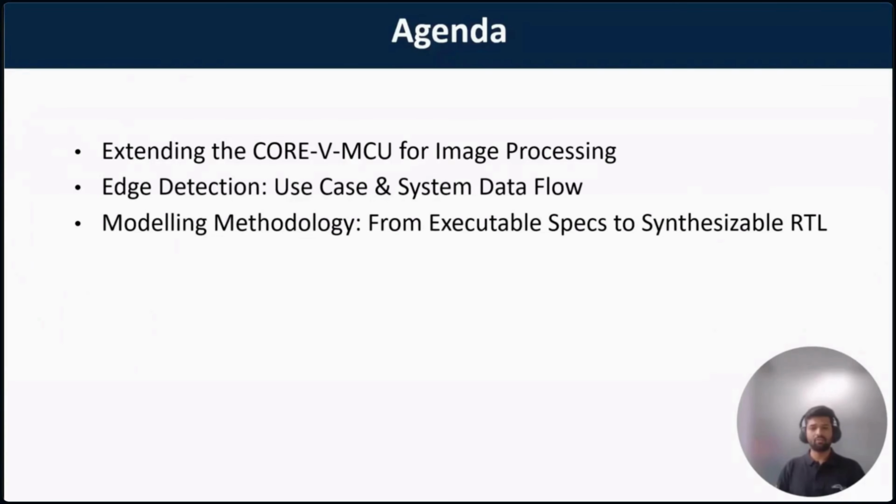In the second half, we'll cover the complete design and verification methodology, moving from executable specs to synthesizable RTL. We will detail the hardware-software co-design cycle using transaction level modeling and high-level synthesis. We will also be covering the performance difference between the loosely timed transaction level model and the high-level synthesis model, and also look at the future scope of work.